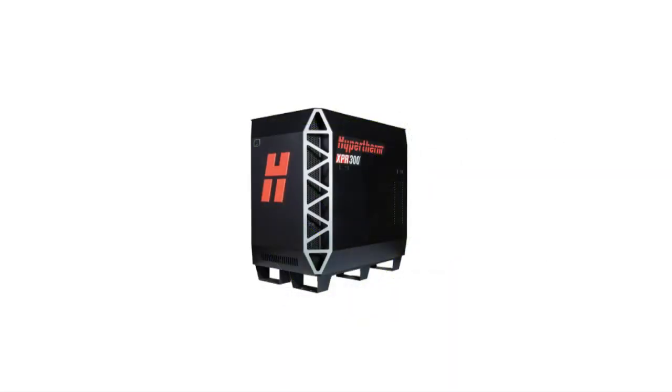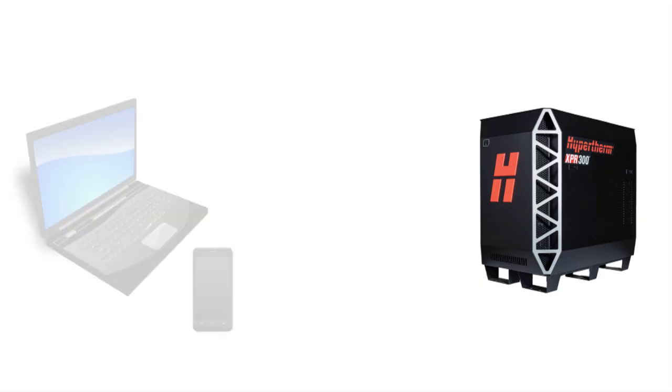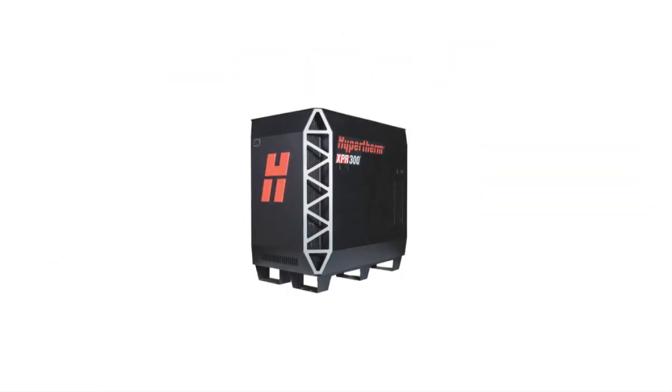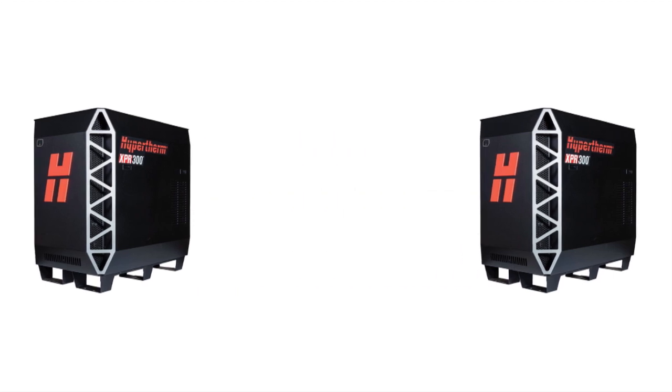What are the steps to connect to the XPR web interface? To connect a wireless device to the power supply, you must have a computer-based device with a screen, modern web browser, and wireless access. There are two ways to connect to the system: access point or AP mode and network mode. In AP mode, each plasma power supply has its own connection. You can only connect to and control one plasma power supply at a time.